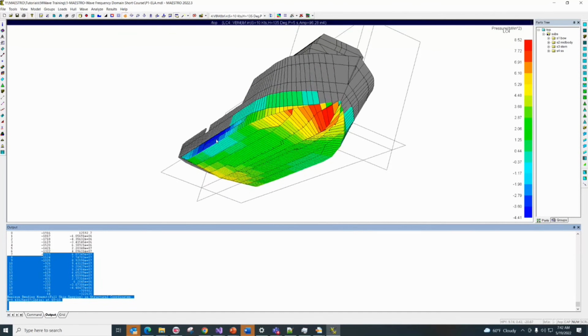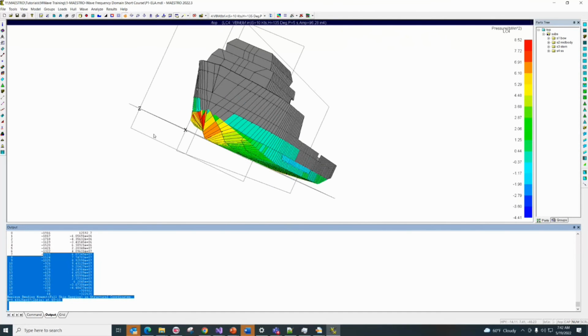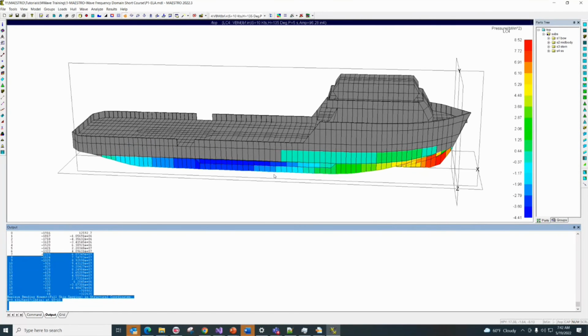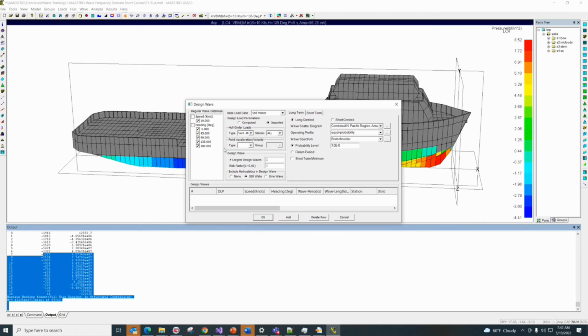It's a little oblique sea. One side has more pressure, the other side is less. Bending moment is not the largest, but there's a little torsion. Could be another worst case. But maybe when you do the design wave, when you do the longitudinal torsion, it's possible to cover that case. After a while, you probably just need one. When you have too many load cases, there are a lot of cases to analyze. Even if you do the first 5, you have 10 load cases. If you keep adding different DLP, then you have more load cases to run.